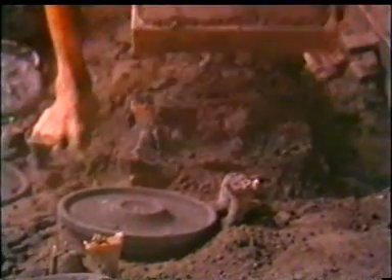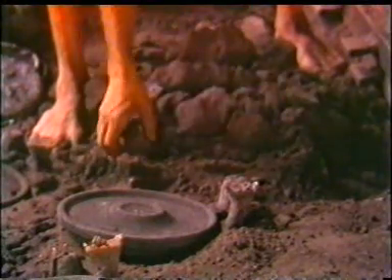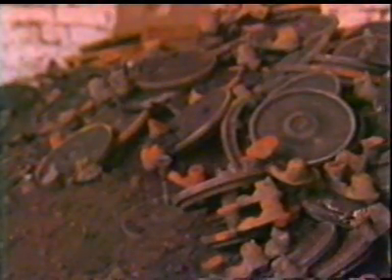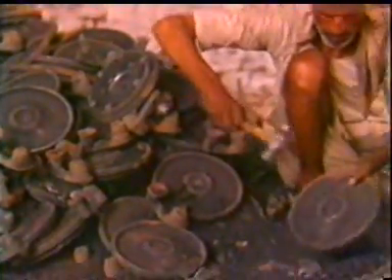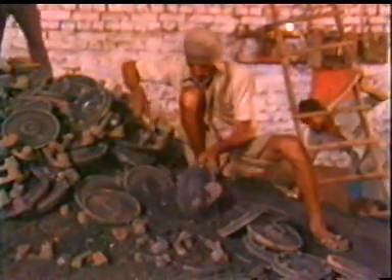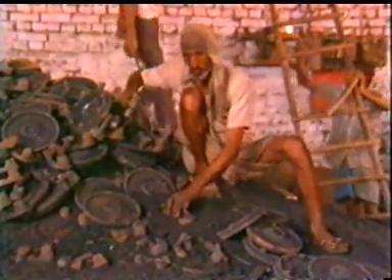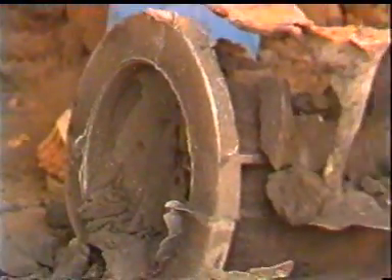After allowing the metal to cool and solidify in cavity, the molds are broken. The extra metal like runner, gates and risers are hammered off from the main casting. The burnt pieces of core and mold sand remaining in the casting are also removed.